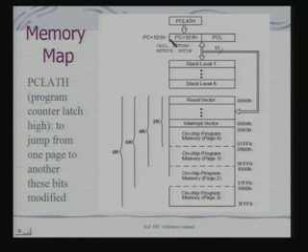So, I have got the PC. How many bits does it have? 13 bits. Out of these 13 bits, a part of it is mapped to what is called the program counter latch high register, and it is connected as per the architecture. Also, you remember it is connected to the hardware stack, and through the 13-bit bus it is connected to the register bank as well.